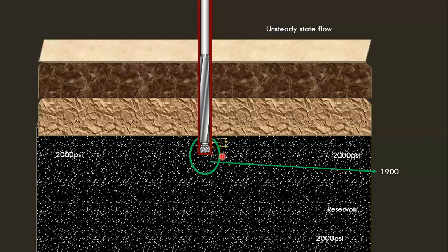Because of that, oil will start to produce from the reservoir. There should be some pressure difference to produce oil from the reservoir. So the pressure reduction should make flow happen from the reservoir drainage boundary to the wellbore. That is how the oil will start to enter into the wellbore, by pressure difference. This might have taken 1 hour, or any time it could take, to reduce the pressure from 2000 to 1900 psi. So that is the green pressure wave.